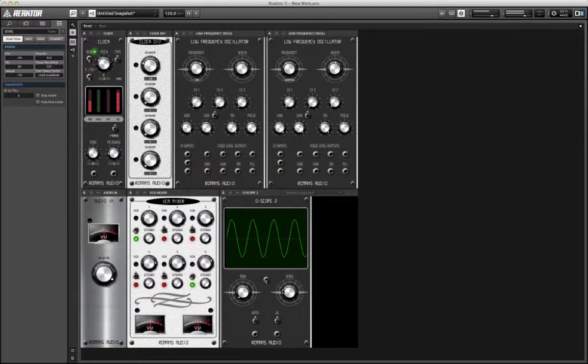All CV in System 63 ranges from -1 to +1. It does not go outside of that. If you find something that does, let me know, because it shouldn't. Everything is -1 to +1 for CV. Any multiplication above that happens within a single module, and nothing is ever passed that is greater than or less than -1 to +1 volts.